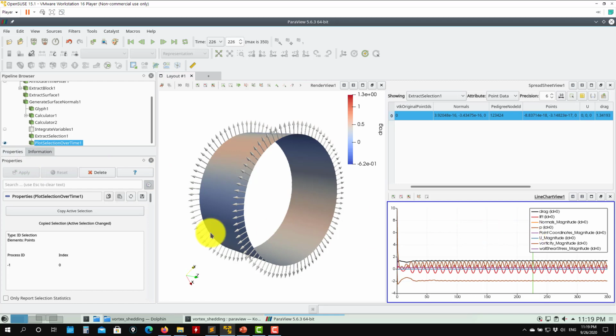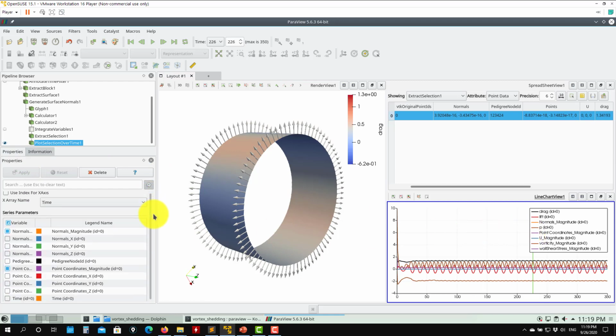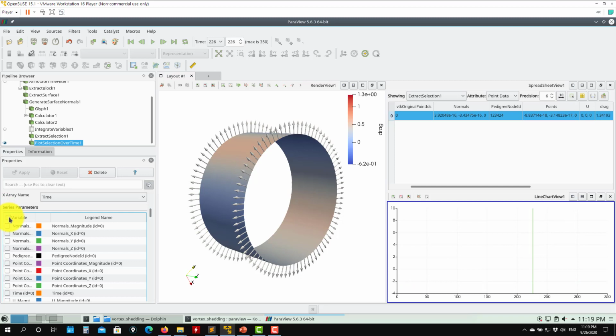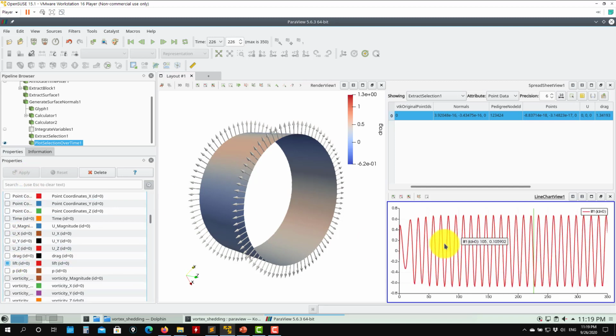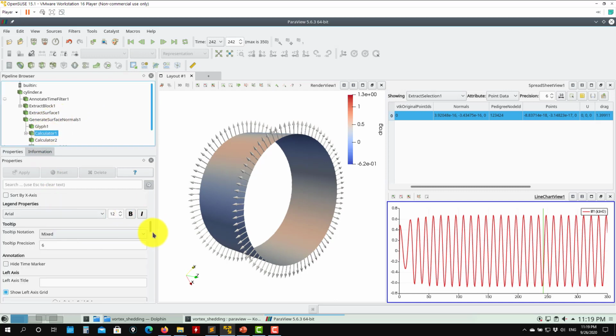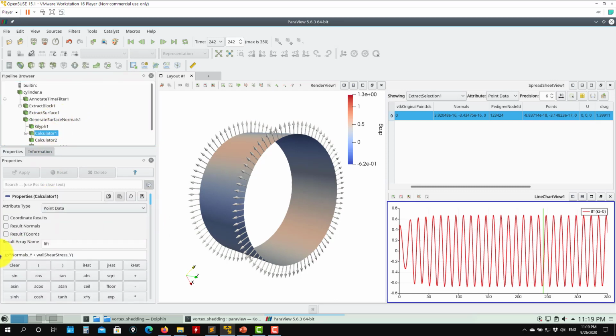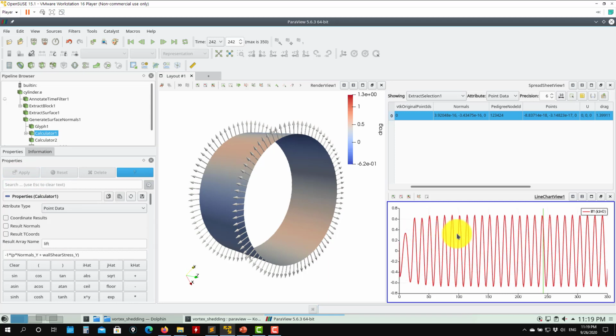And now you have that. So you select there, and here you can choose what to plot. As you go here, you have lift, and see that this is the lift signal. If you press play, your lift. And what I was telling you is that you need to be careful of that sign. Sometimes you need to multiply by -1. In this case also, so -1, and see that you are only changing the orientation here, so nothing else changed.